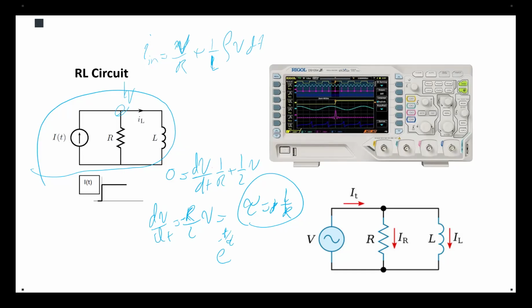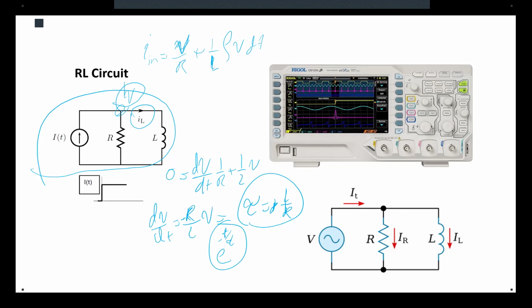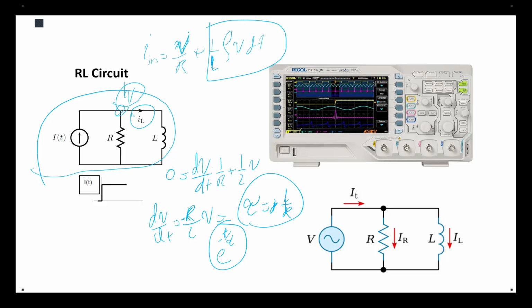You already have that in Calculus 2. So you run a KCL and find the value of V, but this is not the parameter that you want. Your parameter is the current of the L. Remember, the function that you find is the voltage across the L, so you need to take an integral to find the current. Then you have your final function, and you can put the times that you need in that function and find the values. Are we good?